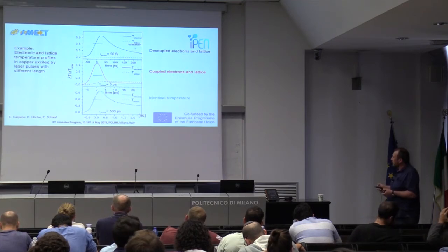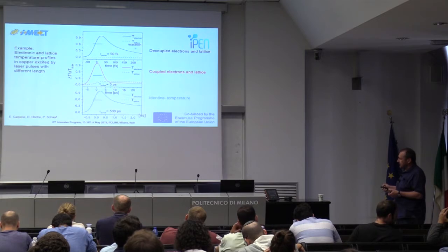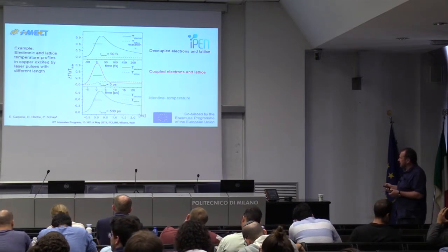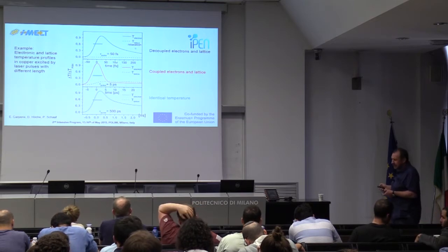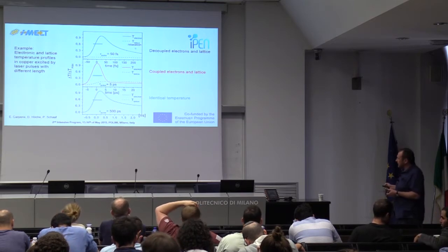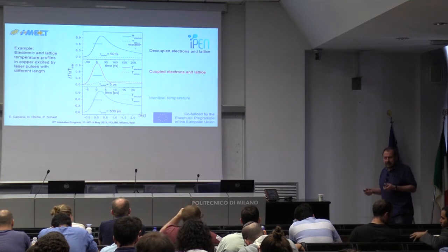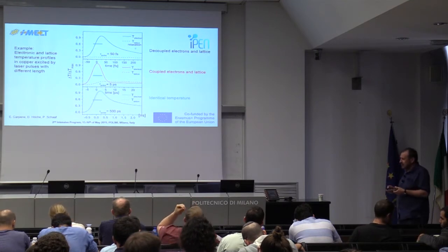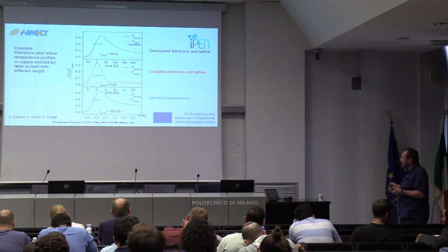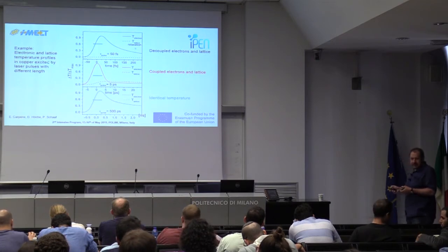And now here you see how the temperature of the electron subsystem increases very rapidly, and then it starts to decrease, and the energy is very weakly transferred to the lattice. It's mainly taken away by ablation; you're just blowing the energy out of the material without heating the lattice. In the second figure, we have an intermediate situation.